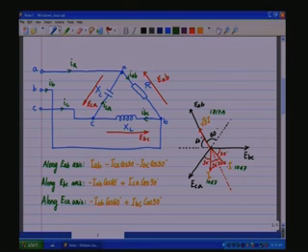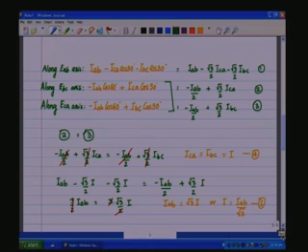So, there will be a projection on this axis that is negative, that will cancel out and give only the active power. There is a projection on this, and there is a projection along this, which will all tend to make it into a nice balanced load as we perform the calculation, so that this is equal to this is equal to this.